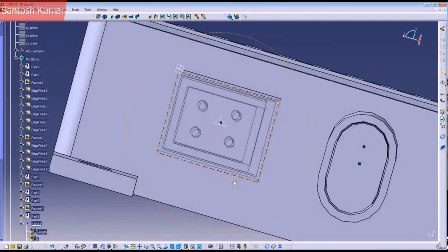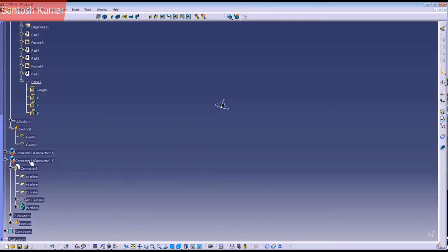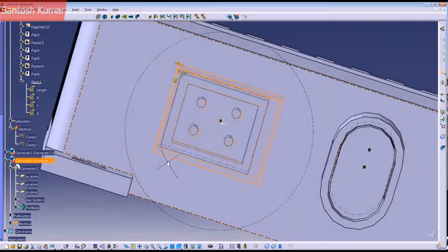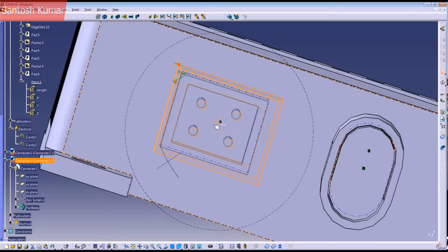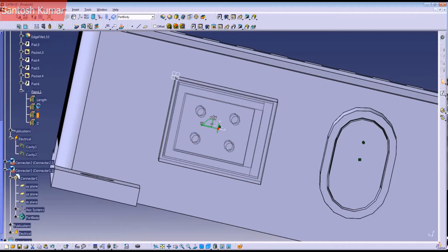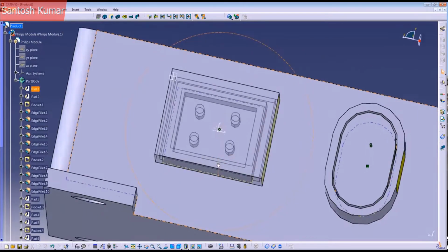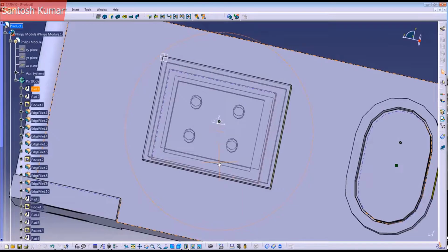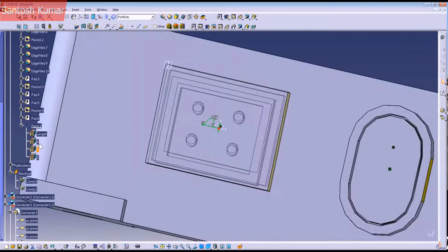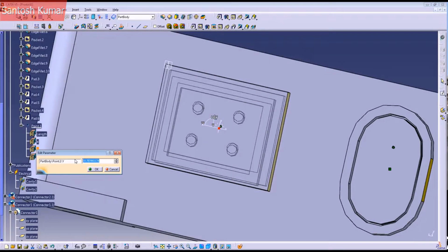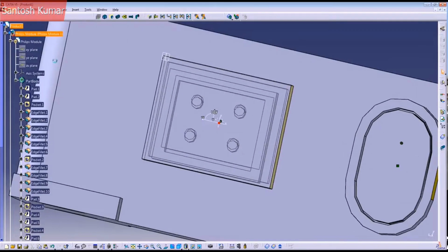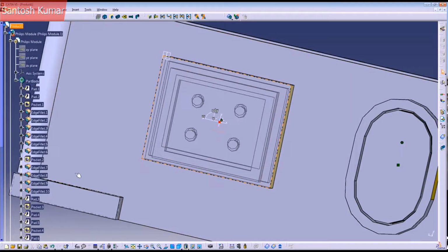But as you can see here, it's not aligned yet. We need to move the connector more up. So we need to change the Y. Let's see what happened. Just keep playing with the coordinates that you need sometimes. As you can see here, it moves up, but it was too much. So just double click again. Just put, for example, 0.5. Let's see what happened.